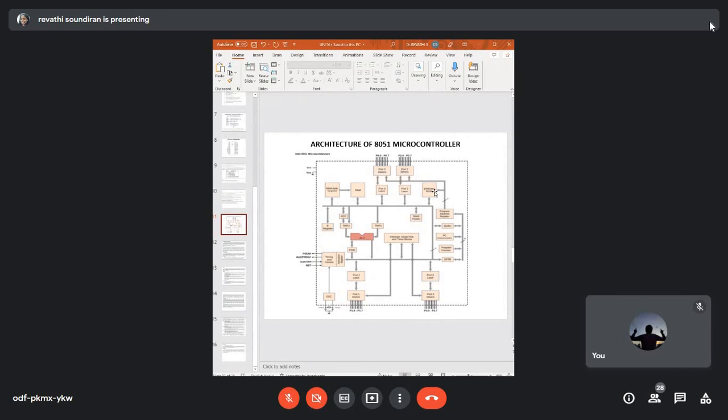Your program counter addresses the program from 000 only, and the higher limit of this is 0FFF. If the program exceeds the internal ROM capacity, there will be problems with fetching the codes from the byte. So when you are writing code for the 8051, you have to understand the specified RAM and ROM allocations by looking into the internal RAM and ROM.